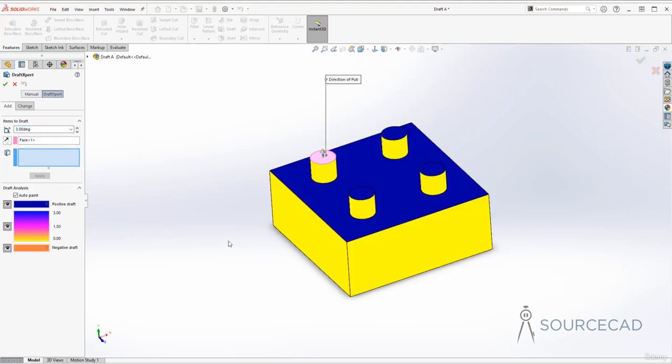But before you do that, you can now see what's going on here. So you can see the draft angle. You can also see where we have 0-degree angle, and actually this will range between 0 to 3 degrees. Whatever the angle you have is specified, that will be the range. So 0 to 3 degree, it's just changing. All right, so with that, let's now select our planes.